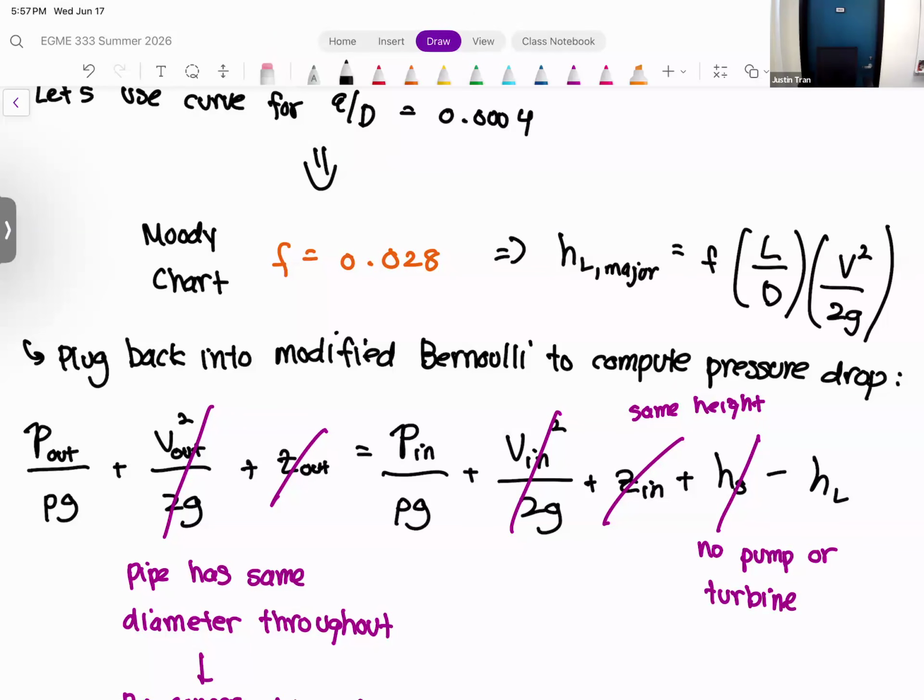Yeah, it is kind of weird to think about. If you do have a change in velocity, let's say you have 10 meters cubed per second coming in and only 5 meters cubed per second coming out. That means every second you have an accumulation of 5 cubic meters somewhere in your system, and eventually that has to go somewhere because mass can't be destroyed. So the velocities have to be the same at the inlet and outlet if the diameters are the same. If the diameters are different, then you could have different velocities. But what has to be the same is the flow rates at both places.